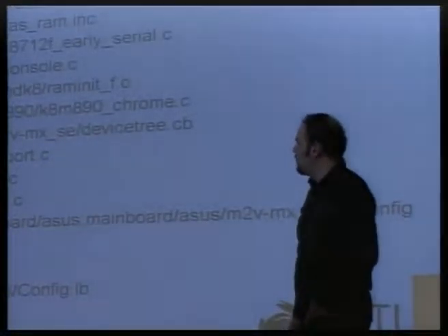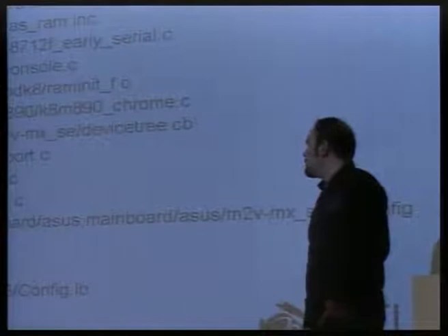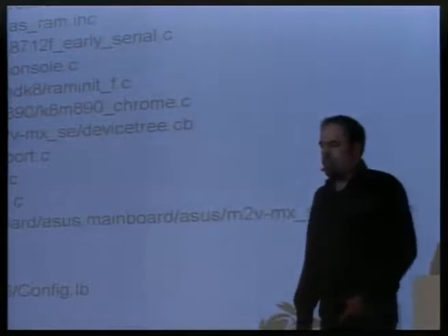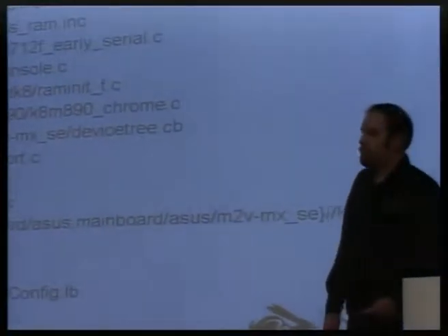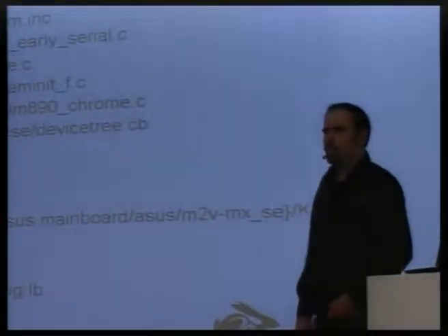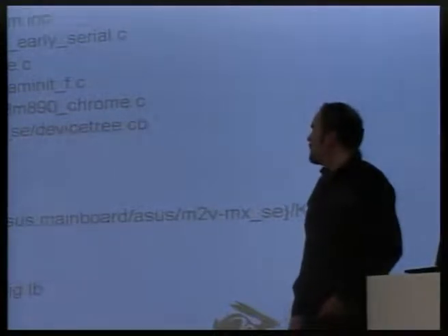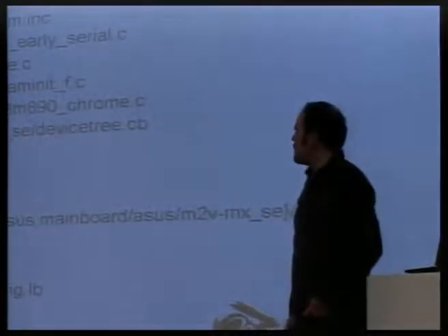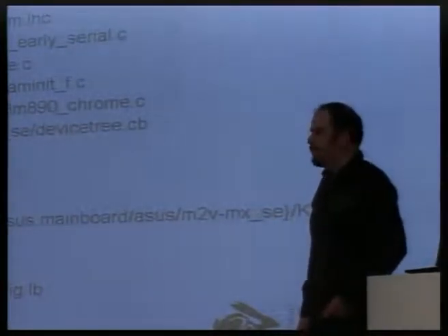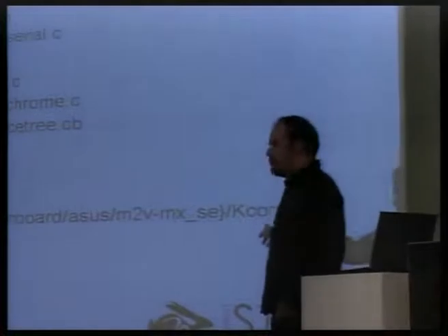There's also a lib directory, which has various bits and pieces, string functions, and also this USB debug direct driver for the USB debug port. Maybe you don't have the Super I/O, but oftentimes you have USB, and in USB 2.0, the EHCI spec, there's this debug port function where you can actually communicate over USB without DMA and only using PCI config space accesses, which is really easy, and you don't, again, you don't have to have RAM initialized to do it, so it's a good debugging method.